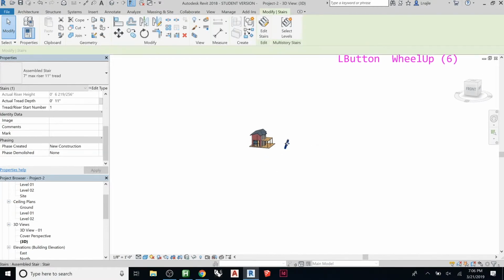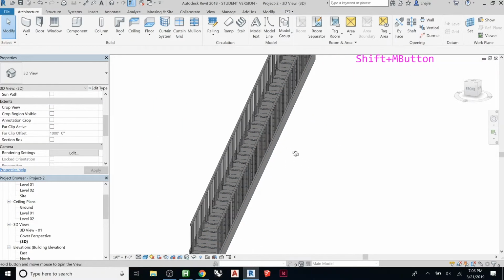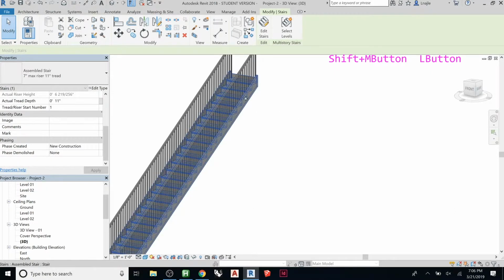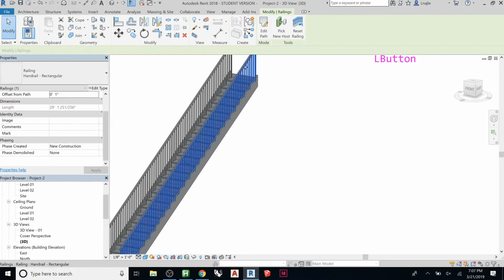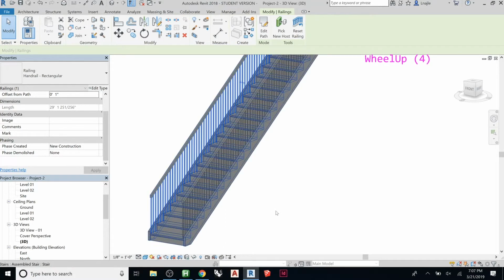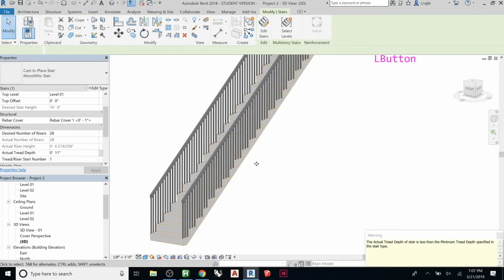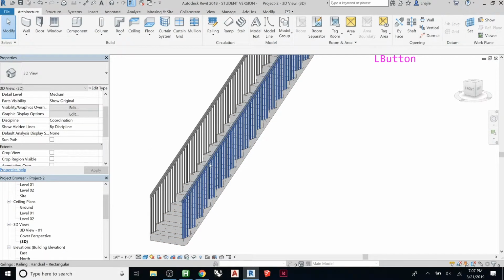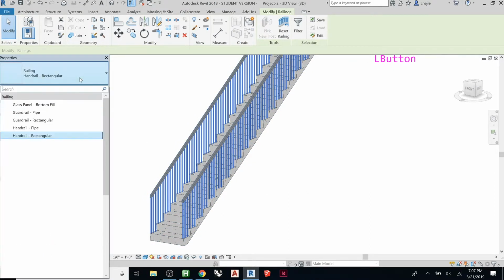So what it's created is this. Just by looking at it, you can see it has all the treads, all the risers, the stringer, which is this guy on the outside, which is what your treads actually span across to, and then the railing. And you can select the railing separately. And then if you look, this whole thing is set to that. If we change it now, it changed that piece, but not these yet. So we can grab those, and it says rectangular railing.